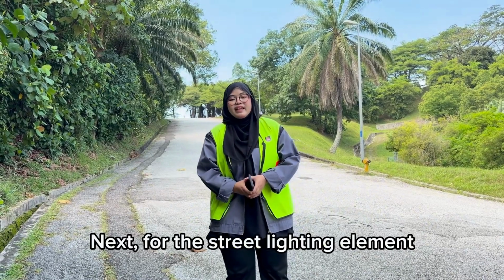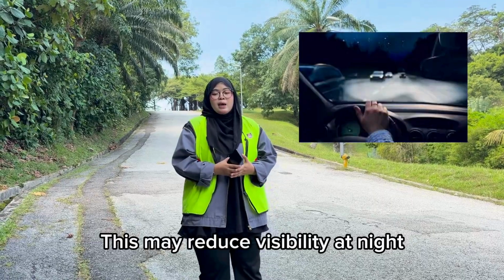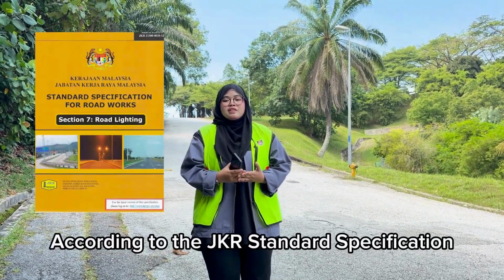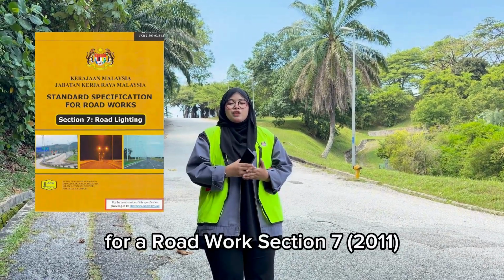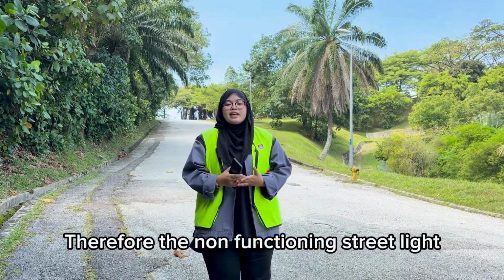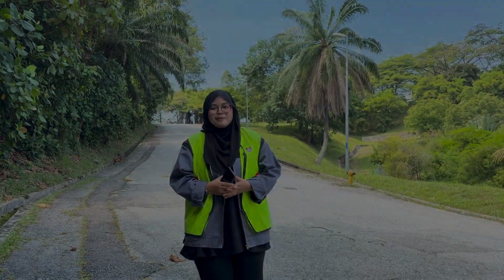Next, for the street lighting element, we observe that several street lights are not functioning properly. This may reduce visibility at night, making it difficult for drivers to identify pedestrians, road alignment, and potential hazards. According to the JKR Standard Specification for Road Works, Section 7, 2011, road lighting should be properly maintained to ensure safe road operation. Therefore, the non-functioning street lights should be repaired or replaced to improve visibility and enhance safety for all road users. Next.